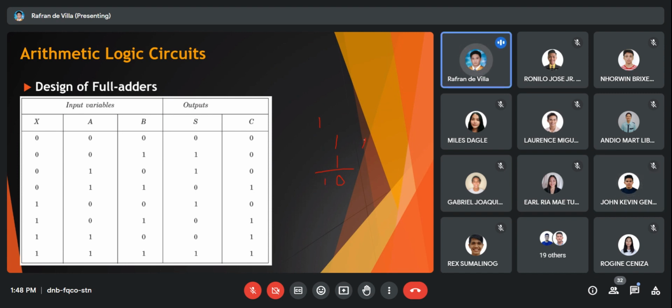So it's just like, guys, A1, B1, so you have your sum 1, and you have another carry 1. So, that is what it represents. That's why this C could act as an output, and that C can also act as an input for the next significant bit.